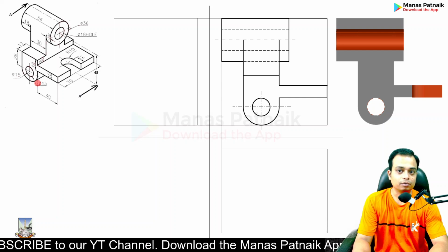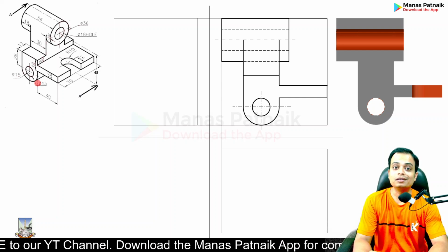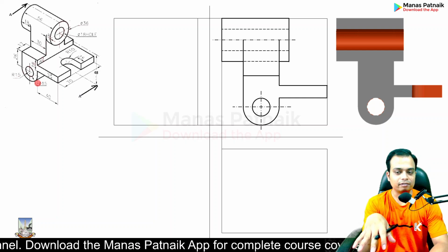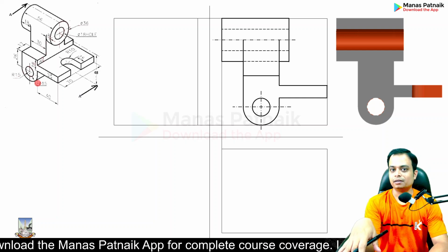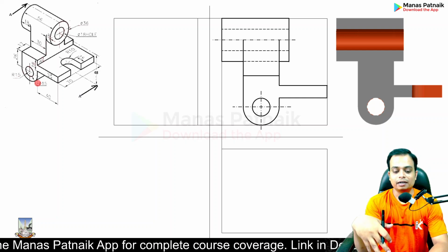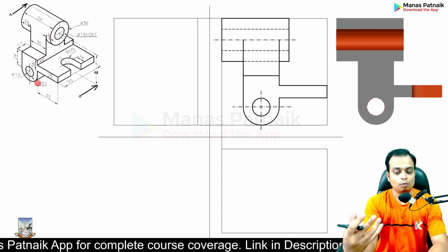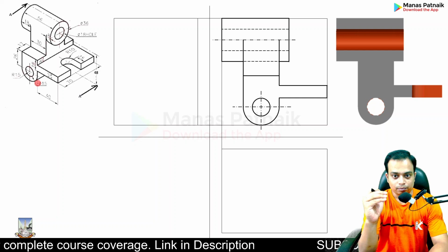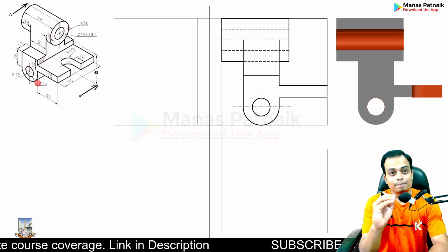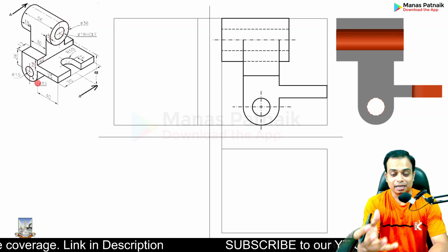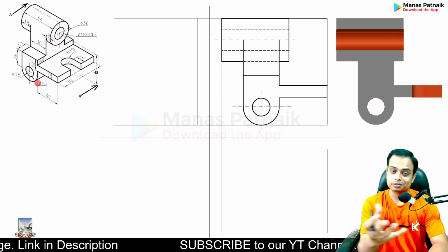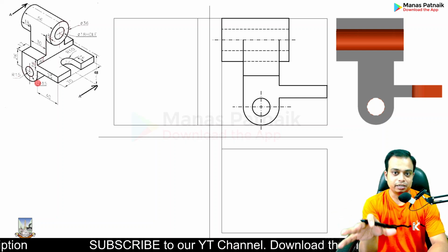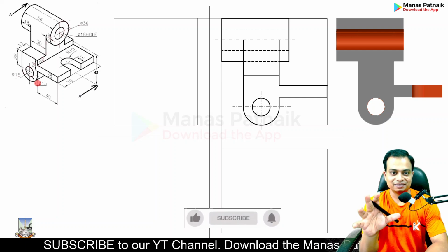That's the front view. Not the section front view. We are yet to do the section. Right? I'm following a sort of unconventional approach. You can straight away start making the section front view. I rather want to show you what happens when you initially start with a front view. Then you see there are so many hidden features which have been represented by dashed lines. In order to get rid of that, what we do is a section, and then how beautifully you can see the inside of the entire machine component. That is the idea.